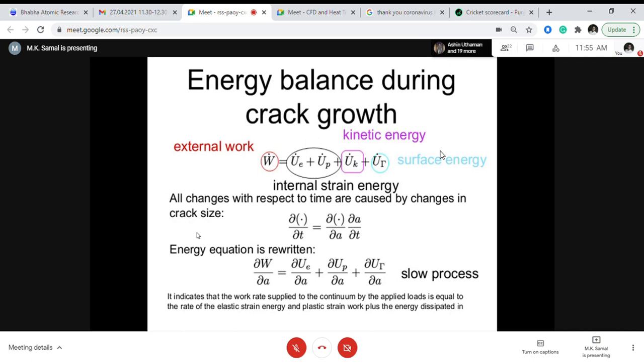This was constant for a given material, and it is for brittle material, and he called it the failure condition at which the material's crack propagates. In the case of brittle material, crack initiation is propagation. So once the crack initiates, it will propagate and failure occurs, unless there is some other mechanism. So he called it the stress intensity factor.